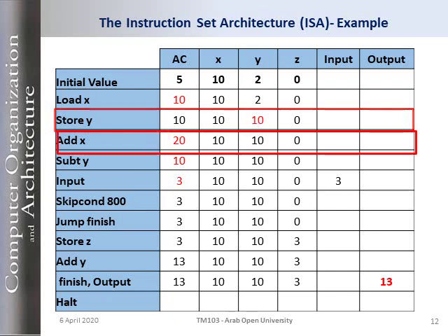Okay, what is our next instruction? Instruction number 3, it's Add X. If you go back to the table, Add X means get the value stored in X and add it to the accumulator and store the result in the accumulator. So what is in X? 10. What is in the accumulator? 10. We add 10 plus 10, it's 20, and we store it in the accumulator. Accumulator will change from 10 to 20.